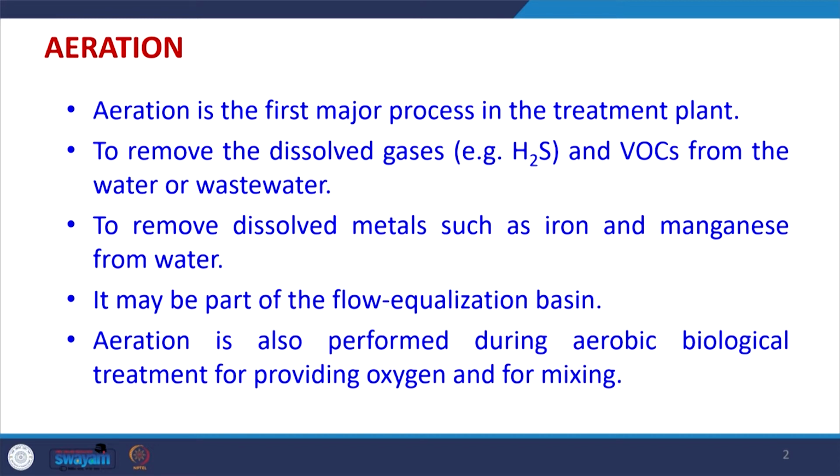And aeration is done not only for providing oxygen, because oxygen is essential for microorganisms to respire, and during that process they use the various pollutants present in the water as nutrients and convert them into CO2 and H2O. Along with that, aeration is very necessary for mixing also.